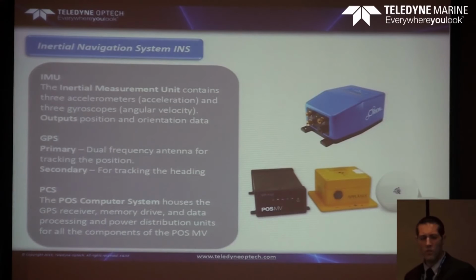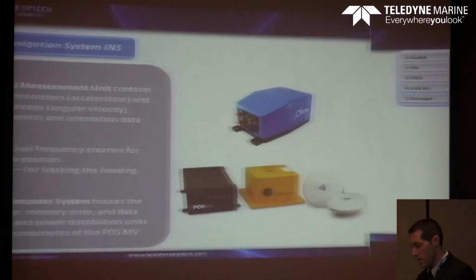As inertial system, we can use any inertial system. Usually we normally use an Applanix, but of course we also use the Teledyne TSS, Orion. Both of them have 3 gyroscopes and 3 accelerometers, and the output is orientation and position. This is a standard inertial system.